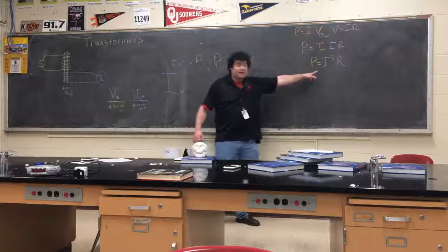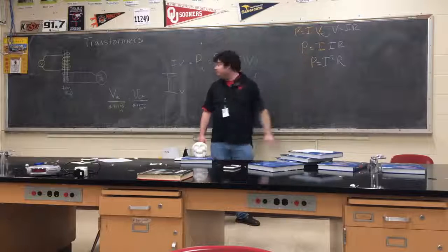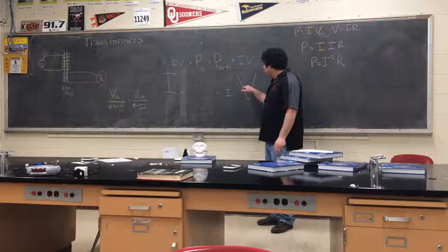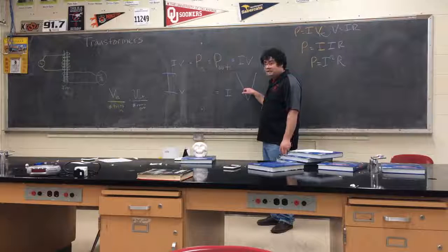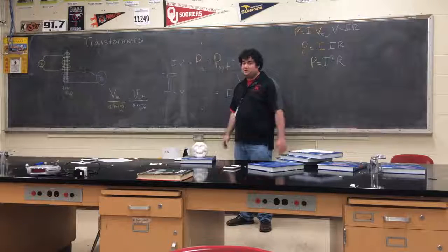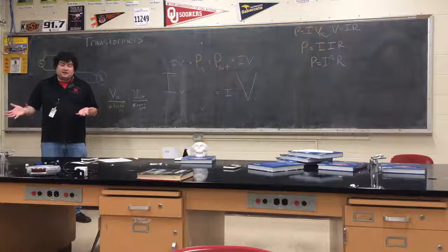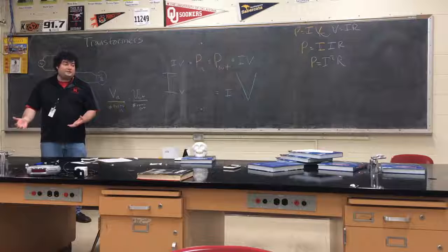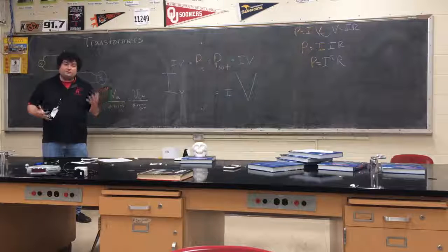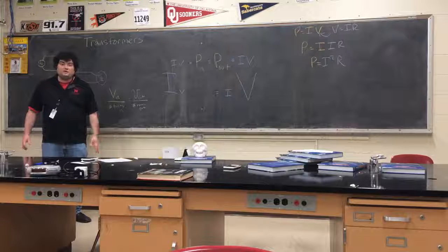So to get around this problem of current being a waste of energy, we can use high voltages to transmit electricity, and then we can use transformers to change those high voltages into low voltages that are safer. In the path the electricity takes to get to your house, it's made at the power plant with a certain voltage. A transformer then brings it up to extremely high voltage, hundreds of thousands of volts, and it's carried long distances on high tension power lines.